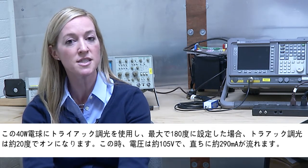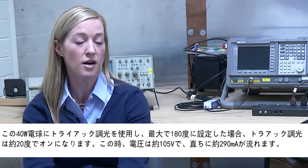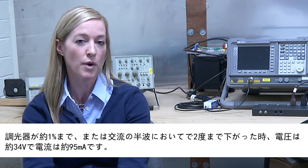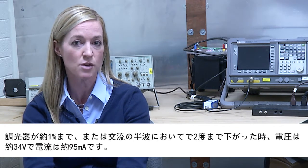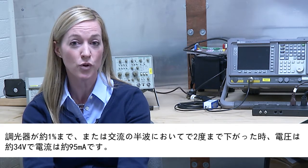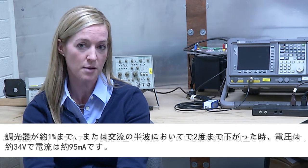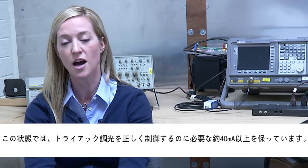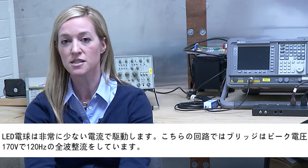At that point, the instantaneous voltage would be about 105 volts and would immediately draw about 290 milliamps. When the dimmer is turned down to about 1% on, or 2 degrees of the 180-degree AC waveform, the instantaneous voltage is about 34 volts and current is about 95 milliamps. This is still well above the 40 milliamps needed for the Triac to operate correctly. An LED bulb draws significantly less current.